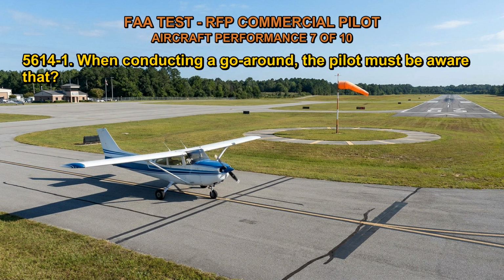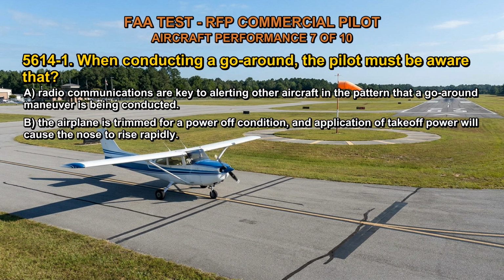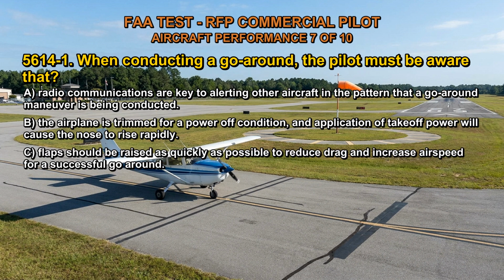5614-1. When conducting a go-around, the pilot must be aware that A. Radio communications are key to alerting other aircraft in the pattern that a go-around maneuver is being conducted. B. The airplane is trimmed for a power-off condition, and application of takeoff power will cause the nose to rise rapidly. C. Flaps should be raised as quickly as possible to reduce drag and increase airspeed for a successful go-around. The correct answer is B.